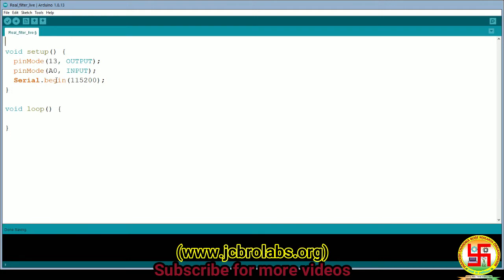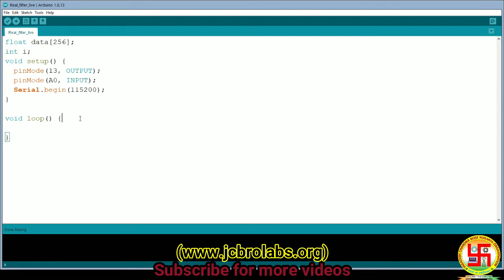Okay, so we will create an array in order to record the entire data. We'll create an array of float type, float data, of 256 samples, because remember, at the starting we'll test with 256, and then we will define int i as well here. Okay, so first of all we will record the data. For i equals 0 to i less than 256. In order to make it more user friendly, we can define the signal length, and then i plus plus.